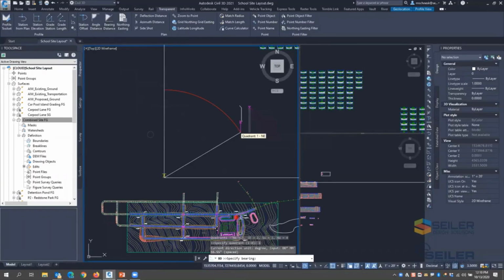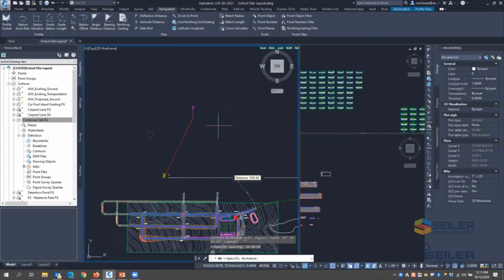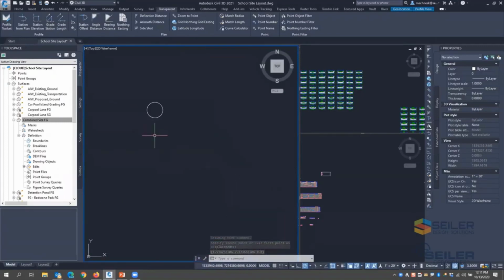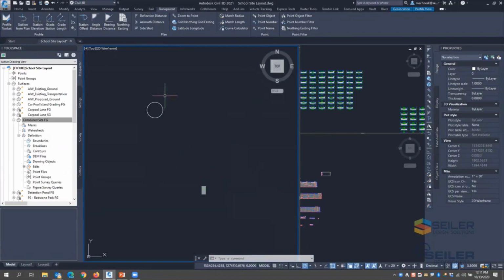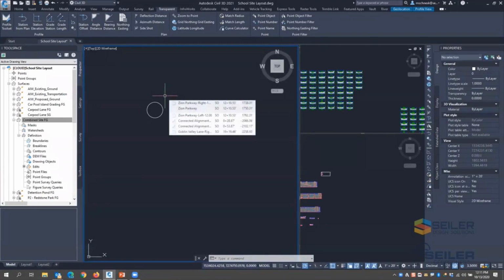So let's say I'm going to move this 25 degrees, 30 minutes, and 45 seconds from north. So I'll put 25, 30, 45 in there, and that locks my bearing. And now I can just type in a distance that I want to move it, maybe 250 feet. And then it moved that particular item along that bearing and that distance, rather than me having to sit and calculate out my azimuth from right angle 0. So that's a starting command.